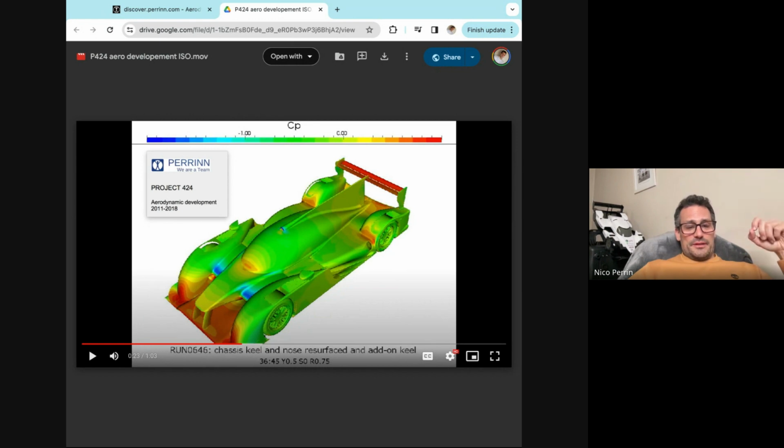Yes, because when you follow Formula One these days, everybody talks about the concept. The concept is basically what your first iteration looks like, and after that, all you do is do these step changes. You try one direction, the next, just one parameter at a time. And what you're doing is basically converging to an optimum solution for that concept. But what you may miss is a better solution with a different concept. So yes, you're right. And this is why the decision on the first design as a concept is so important.